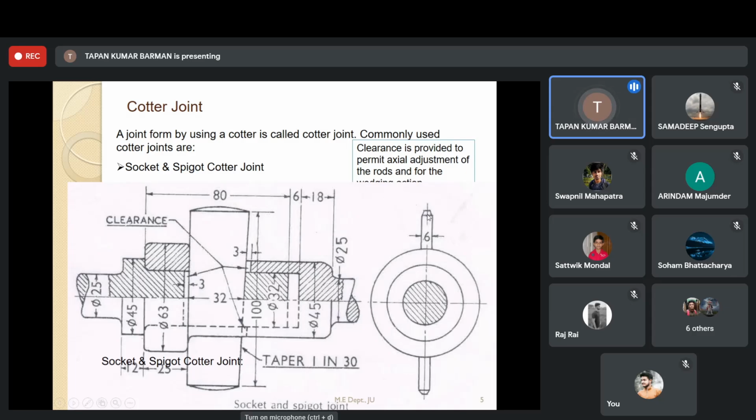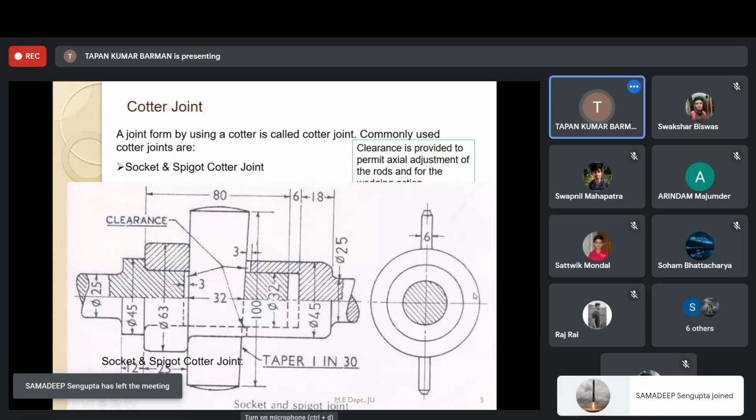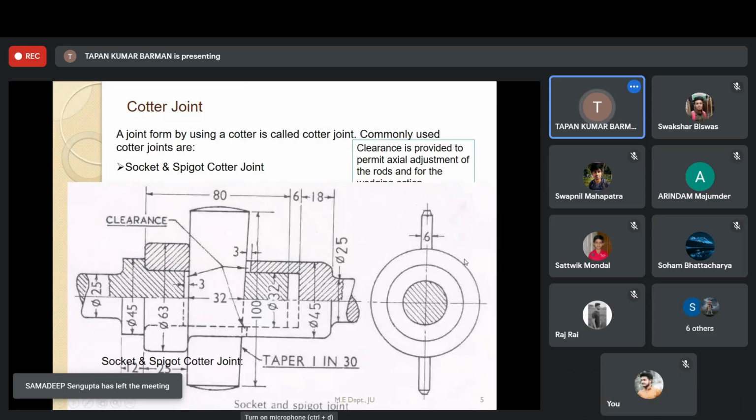If it is full section, then the hatch line should come up to this. For the whole part, if I consider this left hand side component, the hatch line should come up to this to make it full section. So we have not cut the component with full section, but we have cut it with half section. That means this quarter part, if you follow my cursor, maybe this one or this one, we have removed, and we have taken the projection of this component.